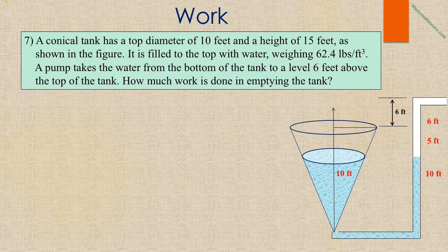Even though the tank starts completely filled with water, let's look at it when it is not completely filled, as shown in the picture. Notice that since water seeks its own level, the water in the piping will be at the level of the tank when the pump is turned off. So suppose the water in the tank is 10 feet high. That means that the water in the pipe is 10 feet high. So when the pump kicks in, the initial amount of water needs to be raised merely 11 feet, not a full 21 feet.